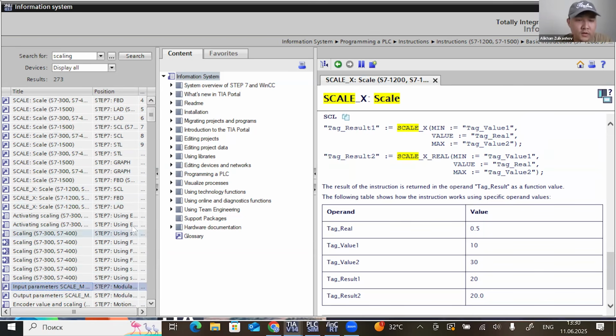Yes, correct. So there is a particular raw value dedicated to spot the bad PV. For example, in case of open circuit, we have a high resistance, right? That's why our milliampere signal will be very low. It will be 0, right? And we can use this 0 milliampere to indicate there is an open circuit.